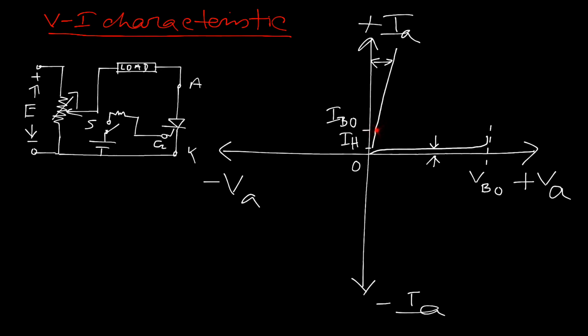Suppose, for some experimental purpose, the thyristor can be on, but it can also be off, meaning the firing is uncertain. When we apply the maximum biasing voltage or critical value, that is VBO, it will reach the same thing due to the application of VBO, that is IBO. That means IBO is a particular amount of current at which the device just starts conducting, right?